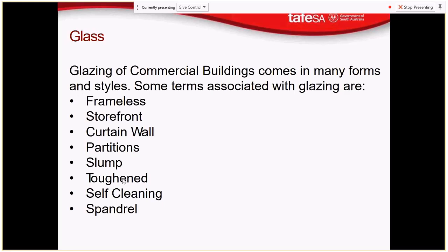The toughened glass, that's the glass for your windscreen. But you'd also use that in a building situation for glazing under 400 millimeters in height. For bushfire areas, you have to have toughened glass for the first 400 millimeters of your glazing if you've got glass at floor level. But it's a good idea to use toughened glass down there anyhow for kids zooming around in little cars and things like that, just because it is much harder to break, and when it does break, it's less dangerous. Vacuuming, yeah, exactly, if you've got one of those big cast iron cleaners.